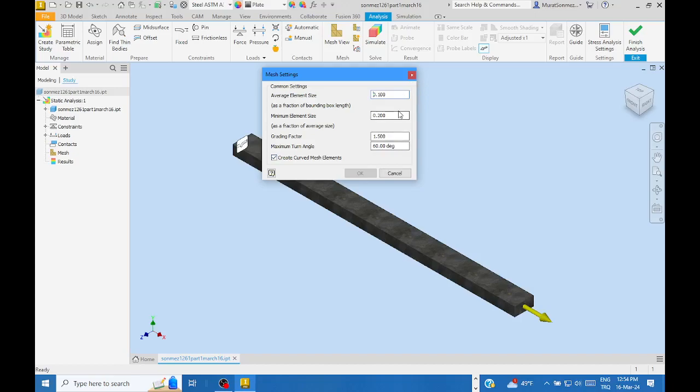But here, in short, I say that for the first trial, keep the default settings of the software. If you decrease the element size, of course, in the limit, make it infinitesimally small, then this means the theoretical solution, the complete solution, not an approximate solution. This means taking it to zero, very near to zero, then the number of finite elements within the body is infinitely large.